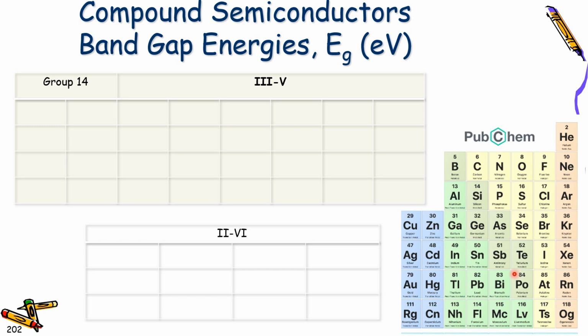Well, professor is wonderful. So can we change the band gap? Because if we tune the band gap, we can have different properties of the materials. Yes, we can. This is called band gap engineering. So for example, carbon, silicon, germanium, and tin, the band gap is 5.4, 1.1, 0.72 and 0.08. So different band gaps give you different properties of the materials.